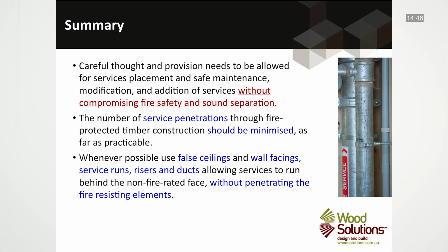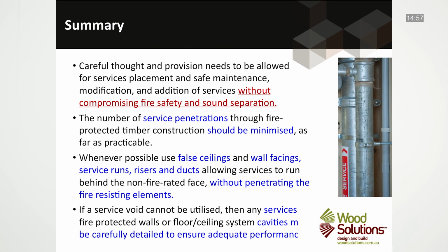Whenever possible, use false ceilings and wall facings, service runs, risers and ducts, allowing services to run behind the non-fire rated face without penetrating the fire-resisting elements. If a service void cannot be utilised, then any services in fire-protected walls or floor ceiling system cavities must be carefully detailed to ensure adequate performance.